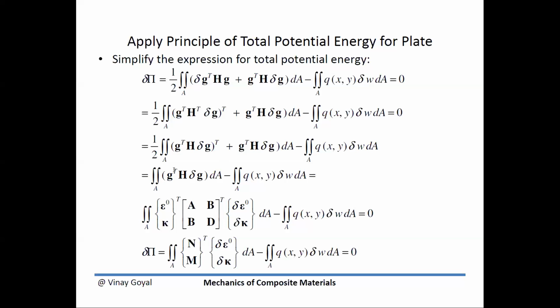And I will now go back to what we had. We had this epsilon superscript kappa, like that. So I'm going back to what H bold was. But now there's a variation in front of epsilon superscript 0, a variation in front of kappa. And notice how there's a variation in front of W, because W needs to be varied as well. And so the first variation pi set equal to 0 got me to this point. Now I'm trying to go back to what I used to have. So this multiplication here is really n bold, n bold. So this is what I got so far.